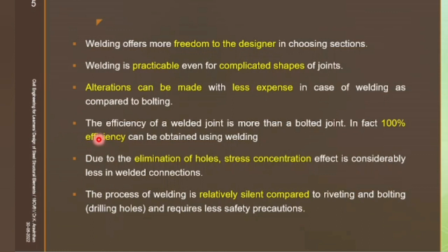So what I mean by efficiency is, due to connecting of two members, you might have the property of lesser thickness. The force will not be transferred completely. That is why you have three forces: forces which are carried in shear, which will be some value; forces which will be carried in bearing, you will have some value; and the plate. Within these three, you take the least component. Yes or no? This is the bolt.